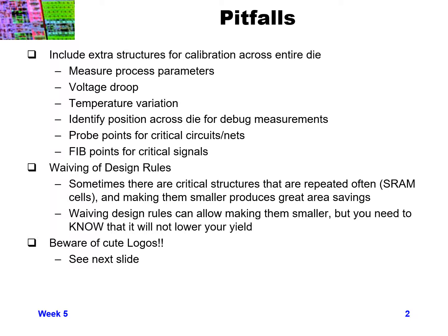But again, this isn't something that can be done on really tiny circuits that are really local to areas. So typically, if you have some place where you have a critical signal where you think you might want to short it to someplace else or be able to change its behavior somehow, you have to create a specific point to enable you to do that with more success. So things like that are additional structures, but you need to go out of your way to identify places to put them and to put them in,